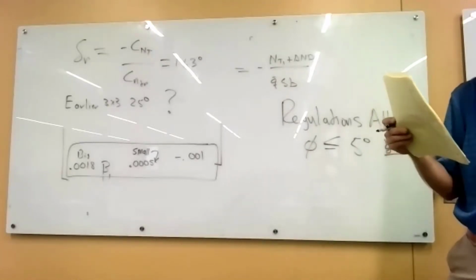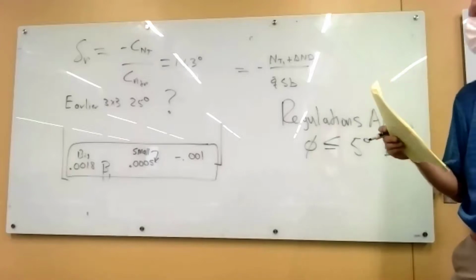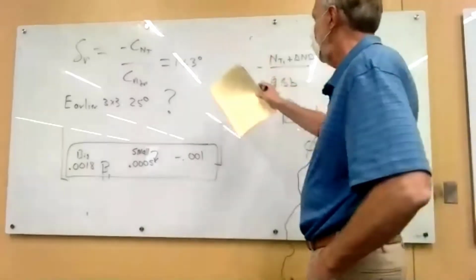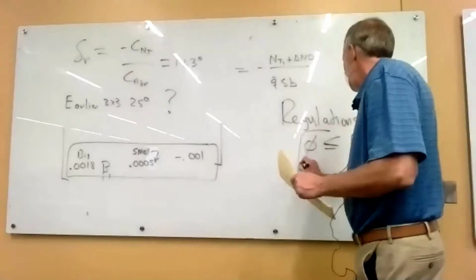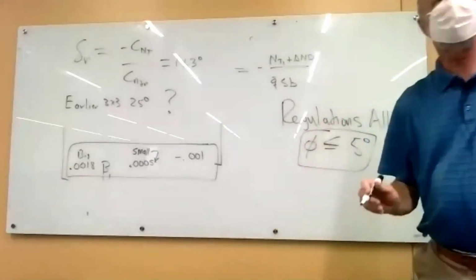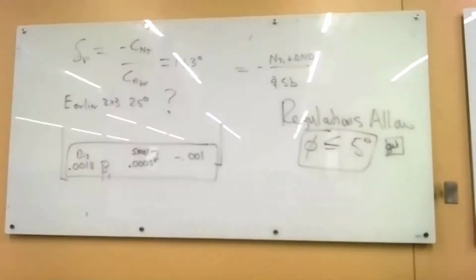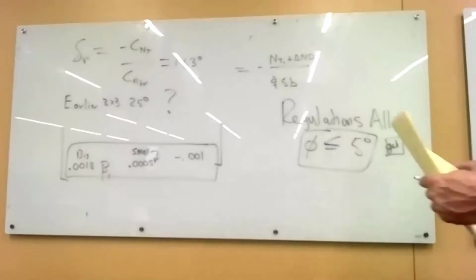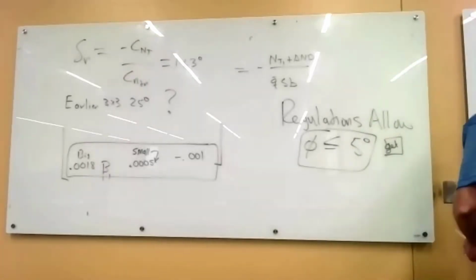So it sounds kind of kludgy, doesn't it? But from experience, they found out that you can use that approximate formula if you allow a bank angle. And where does the bank angle show up? It shows up in that right-hand side, right, for the side force. So if you put 5 degrees of rudder and bank angle in there, let me write that on the board.